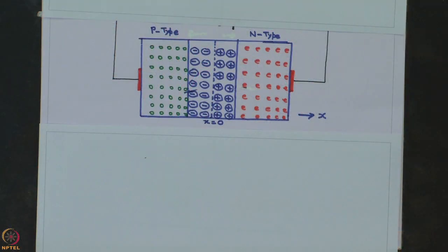So, if you take a Pn junction which is formed by juxtaposing p and n type of semiconductor material, you actually end up with this kind of depletion layer, which will have a field and a contact potential. Okay, so having understood the formation of the Pn junction and the mechanism involved, let us now see how a Pn junction works when an external voltage is applied across it.